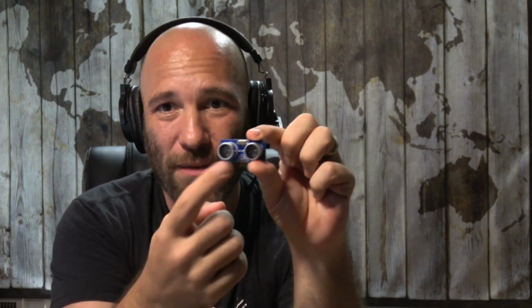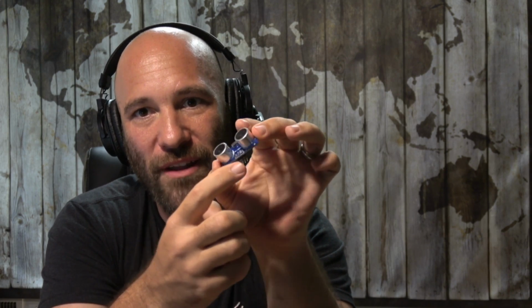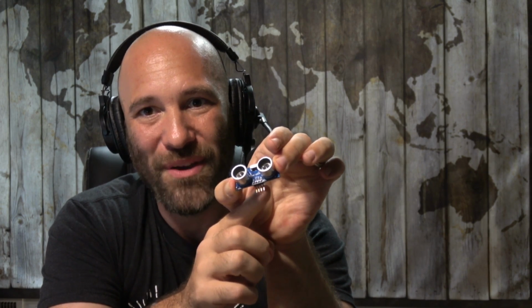This is a proximity sensor here. This is actually used in order to create little autonomous vehicles. And if you'll notice at the bottom of it, it simply has prongs that you can connect electronic wires to. So you can have the Arduino board sitting here in the vehicle, and then you can have wires that run out to this proximity sensor, and then the vehicle will drive around, and whenever it gets too close to an object, it'll stop, and then depending on the code, it will move in whatever direction you want.